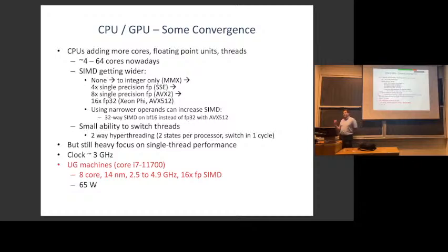So what hyperthreading means, it's a form of multi-threading again. Remember when we were doing streaming compute models? We said if we had a really fast IP core that we couldn't keep busy with one data stream, we could send in 2 data streams and just put a tag in saying you're from data stream 1 or you're from data stream 2. And then after we went through that IP block or that hardware block, we could take the streams apart again. Well, that's what hyperthreading is for a processor.